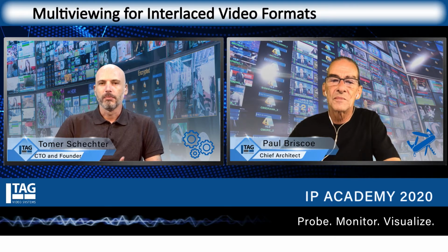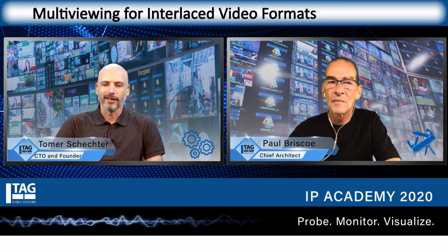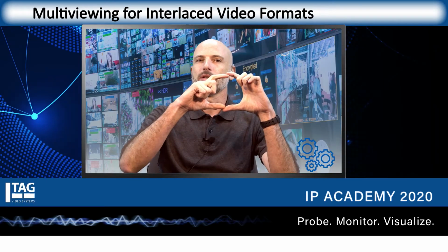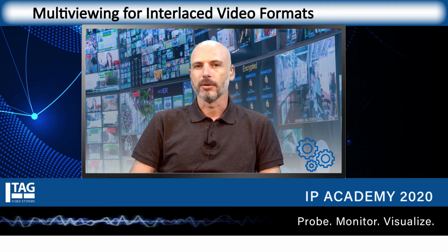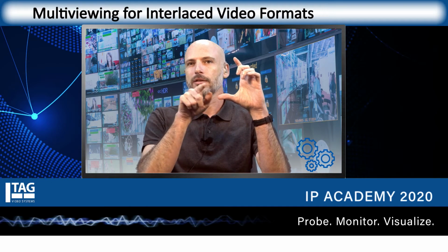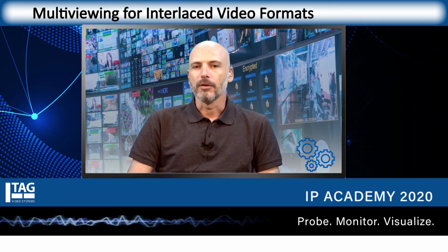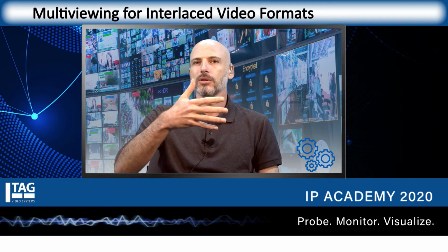When we're going back to MPEG-2, where the real professional compression started, then interlaced is a native part of the content. The content is encoded as macro blocks, 16 by 16 pixel blocks. For progressive content, the scanning just goes along the lines and down. For interlaced, it does the same thing with jumps of lines.